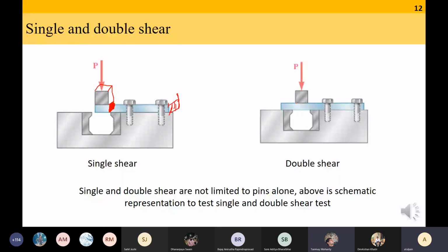We have to divide the force by 2 only when there are two different surfaces, meaning a rectangular slot is there. You can imagine that you are dividing P by 2, or you can say that you are accounting for both the areas. But in the circular case, we take the entire circular area. Actually, we are doing P divided by infinity, but multiplying it by a small infinitesimal part. You can also imagine it like that. It is the same thing that we are doing, but it's a circular hole.